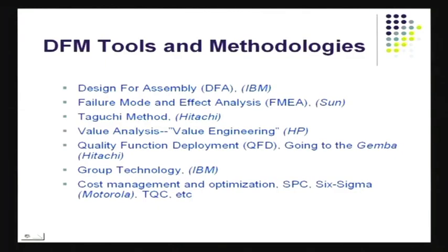Value engineering is also something that, for example, I've listed the companies there. Value engineering is capitalized by Hewlett-Packard as an example. They are the ones who say whatever you put together, it must give some value to the final user. It should not be there only as bells and whistles. If I've put a strange clip on this, it must have some value, otherwise I don't need it. If I've got something fancy inside this pen, I've got to make sure it has added some value to it, maybe life of the ink or something. It's got to do something useful, otherwise it's just a waste, and this is something you'd like to avoid.